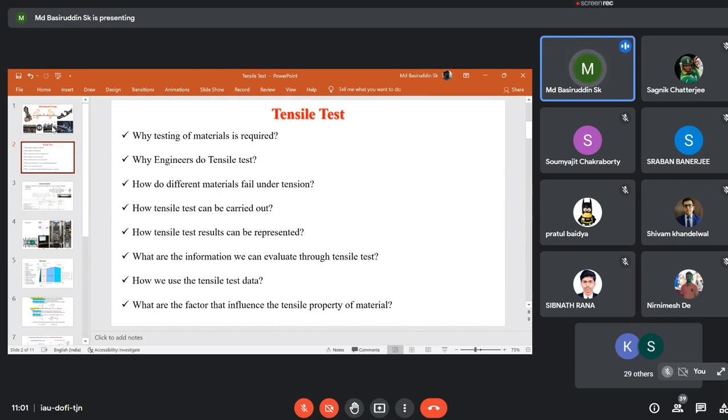So in that particular case, you have to follow a certain standard, whether it is ISO standard, British standard or ASTM standard. I will send you the ASTM standard for tensile test. There you will find the different types of tensile specimen that you can fabricate based on the sample availability and the capability of the machines that you have. If you follow these standards, whatever shapes you follow, you may get